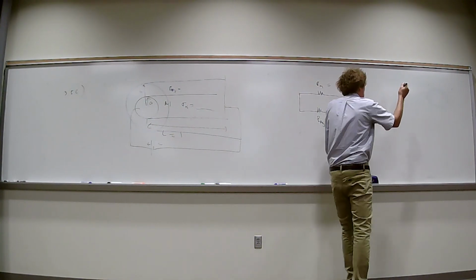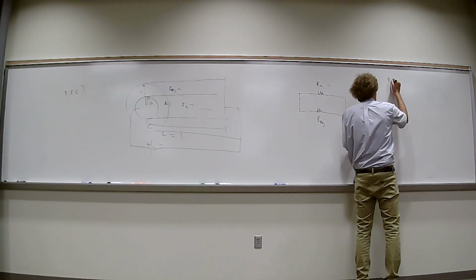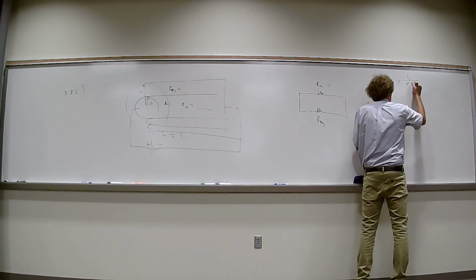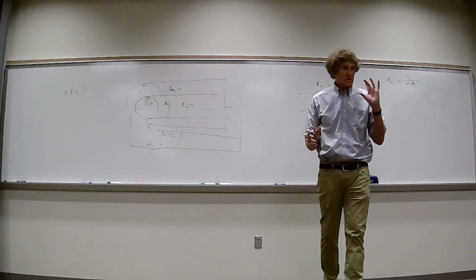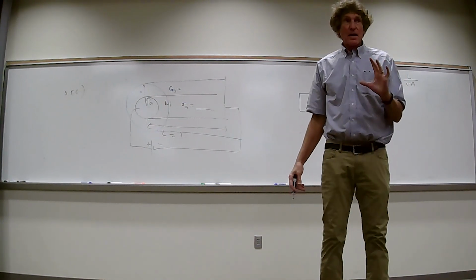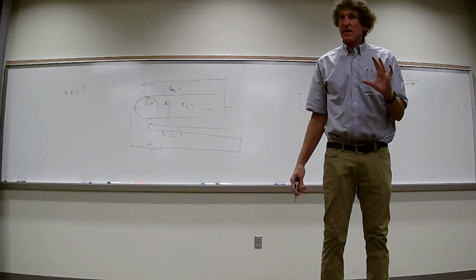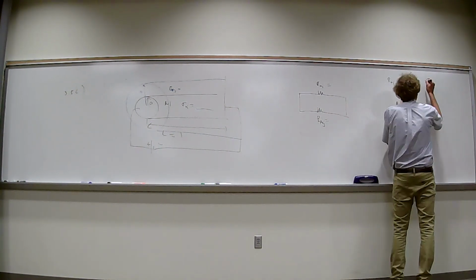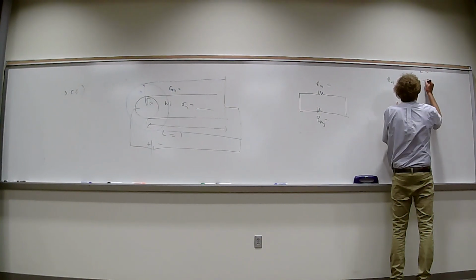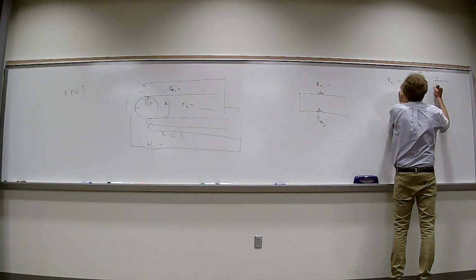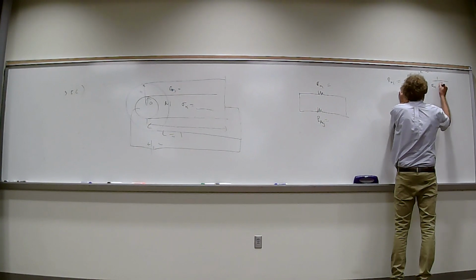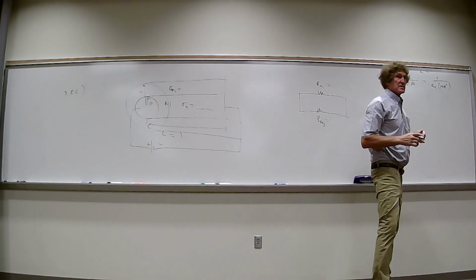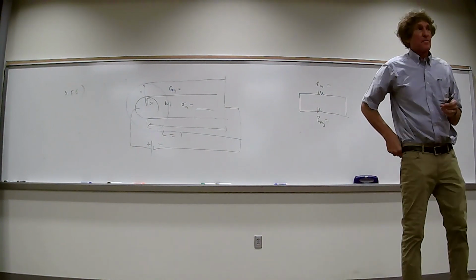All right? So this is per meter. R nickel is again L over sigma A. I'm just putting the general form: constant cross section. Two wires, the cross section doesn't vary. Since it's per meter, you can just say L equals 1. This is going to be 1 over sigma of nickel times the area, which is pi a squared, and we put the radius of the nickel wire down.